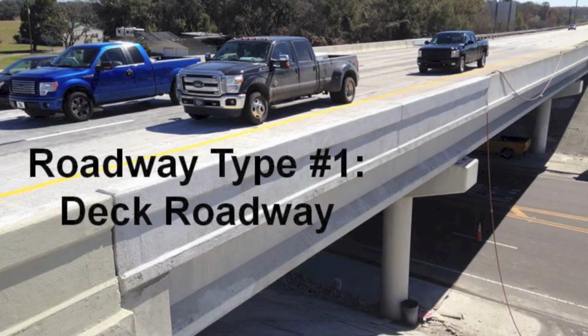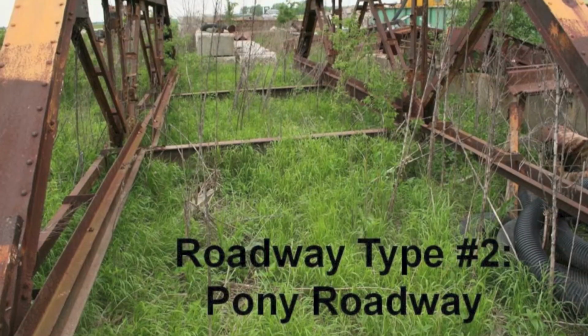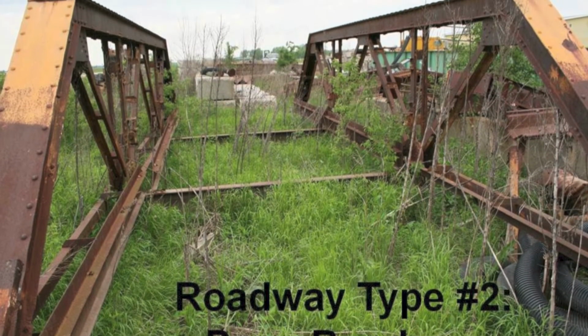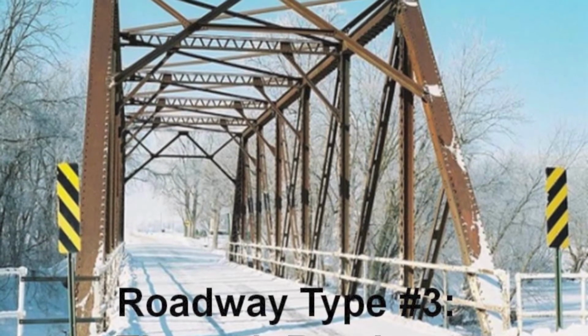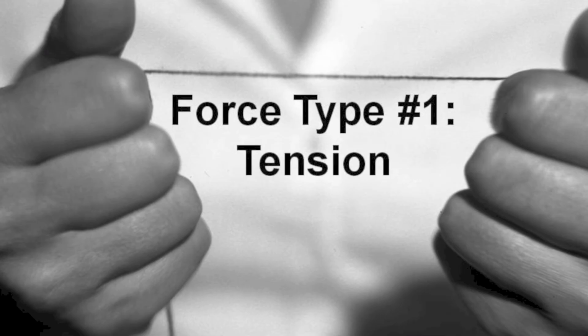For bridges, there are also three types of roadways: deck, pony, and through. A deck roadway is where the cars drive at the highest point on the bridge. A pony roadway is just like a through roadway, except the material above the roadway is not connected. A through roadway is where there is excess material above the roadway on both sides that are connected by bars extending straight above the roadway.